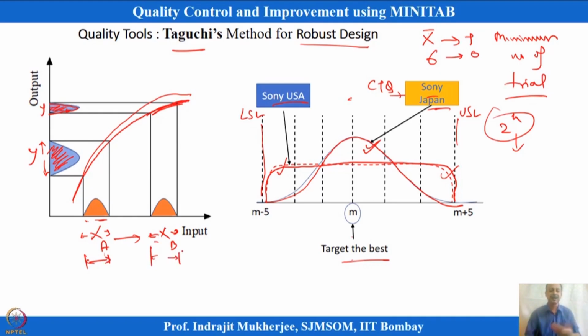So, that is the idea Taguchi was emphasizing: there is a nonlinear region where, if I can shift the x condition to that region, then my variability in y also decreases, and it also brings the response to the target value. Here we are only showing that variability is changing like that; we can bring it to target values by other conditions, by using other options.